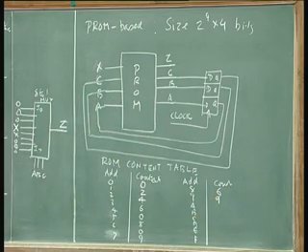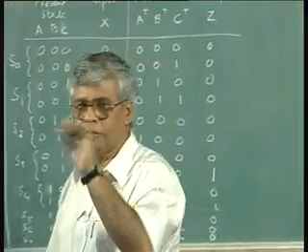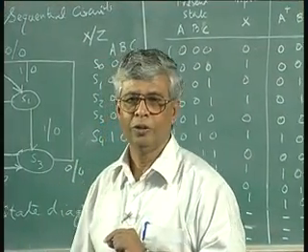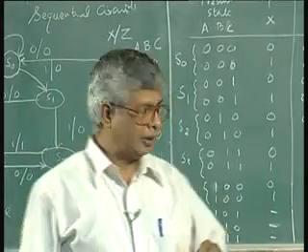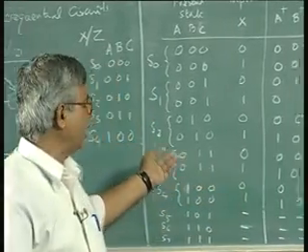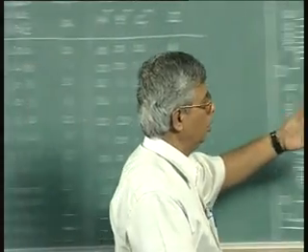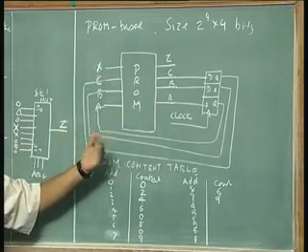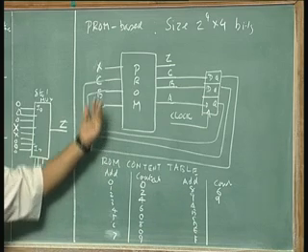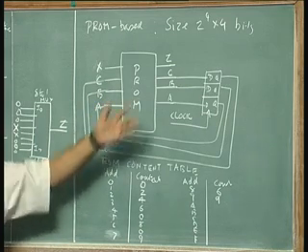How do you put a don't care in a ROM? How do you give a value and put it? I can't write a don't care into a ROM. I have a ROM, I give an address and the output comes. Whether a state exists or not, if I give an address, the corresponding word will be read.